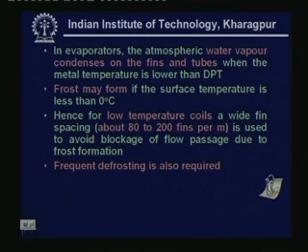And in the commercial evaporators, you will find that the fin spacing may not be uniform, especially if the fin is not plate fin tube type. Typically in domestic refrigerators, the fins are provided in such a way that at the inlet where the frost formation is much faster, the fin spacing is higher. And as the air gradually moves up, the fin spacing is gradually reduced so that you can have higher heat transfer. So this is a very important aspect to be considered in the design of evaporators which are likely to get frosted. And since you cannot allow the frosting to take place continuously, frequent defrosting is required.